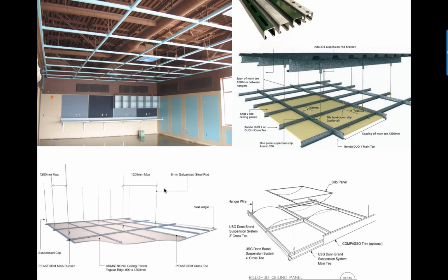Or off of a ceiling grid, although most of the time we're not designing custom luminaires that go into these ceiling grid systems. However, if they are, by all means, that's fine, but you'll, again, want to look at the details of the grid system or of a Unistrut system or a fixed metal stud type of ceiling system.